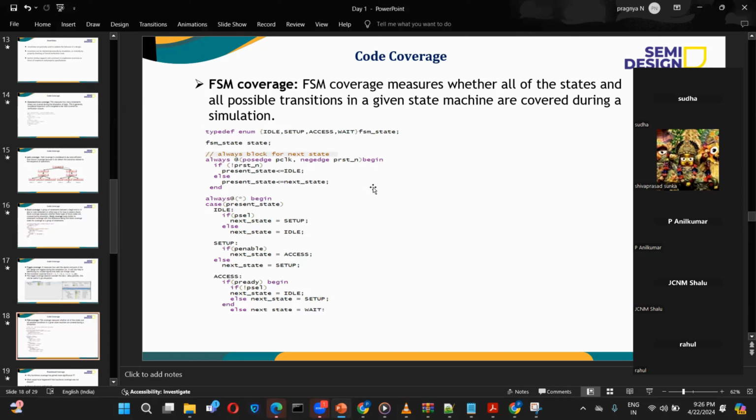Before doing any coverage plan, in most of the industry, if you are assigned some coverage task, they will ask you to create a coverage plan. How will you create the coverage plan? First you will understand the entire design or the specifications. Through that, you will have a rough idea initially for a coverage plan. Later on, you keep on increasing that based on your understanding, which keeps growing as you work on the project further. Then you have to update your coverage plan.